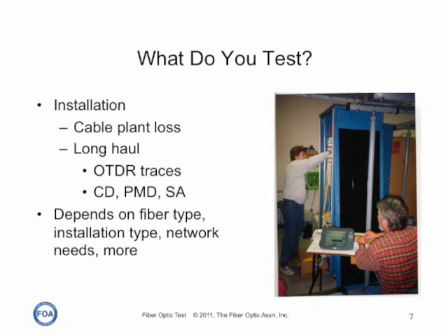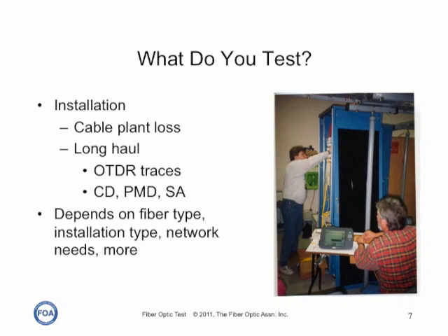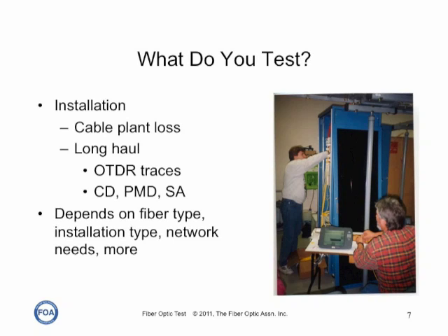Very long systems will test chromatic dispersion, polarization mode dispersion, and typically spectral attenuation because they'll be running wavelength division multiplexing. The actual tests involved will depend on the fiber type, the installation type, the network type, and more.